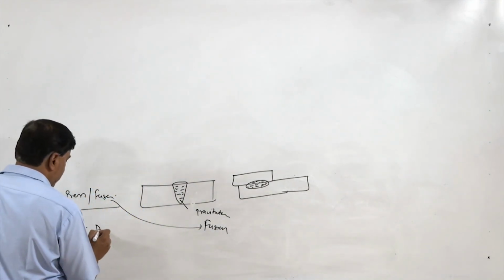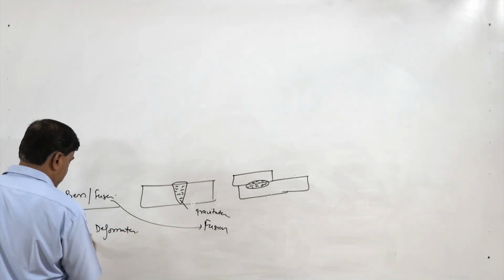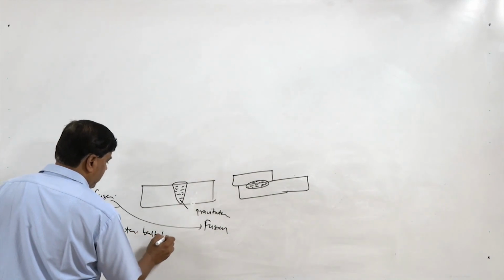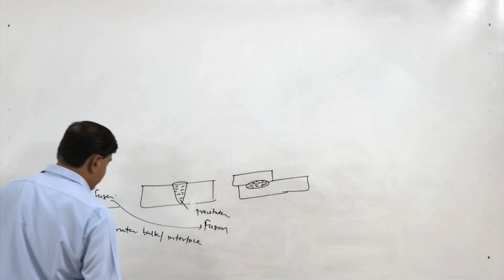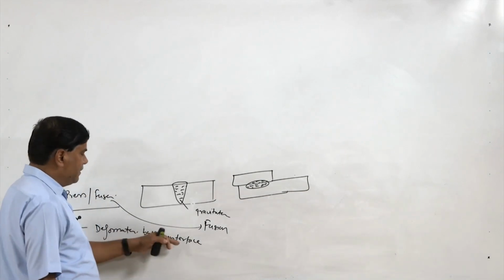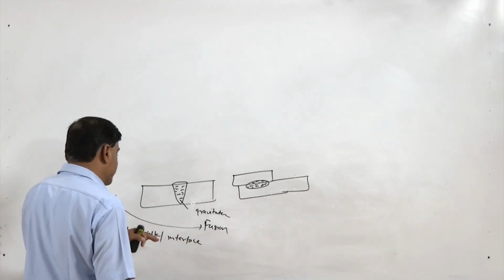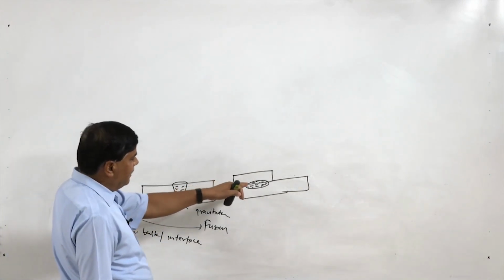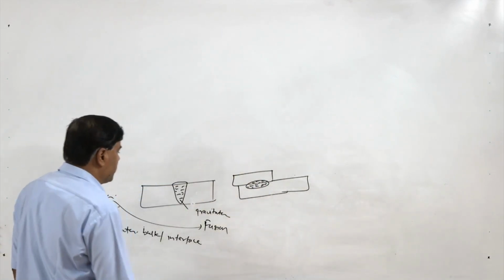So, pressure welding involves the use of either bulk or interfacial deformation for developing the joint, like ultrasonic welding, friction welding, explosion welding; all those come in this category. Resistance welding processes too, because even if the molten metal is formed, it solidifies in a very confined situation.